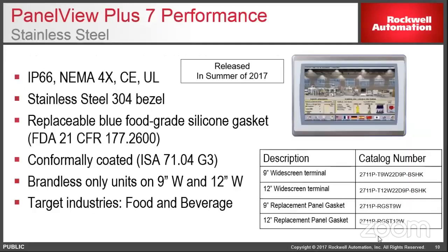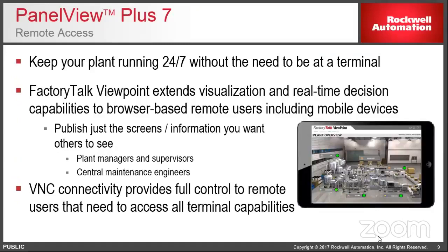Unlike VNC, Viewpoint is a separate product from Rockwell, but you get a built-in license for the PanelView Plus 7, where you can not only remotely access your PanelView Plus 7, but you can actually publish special screens when you're designing the application. You can take your current application and push it to the panel, but you can also set special screens that can only be seen through Viewpoint.